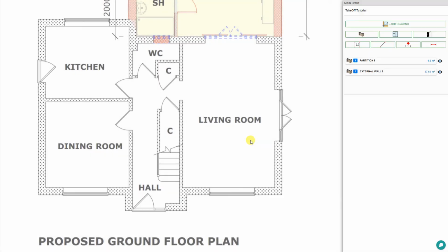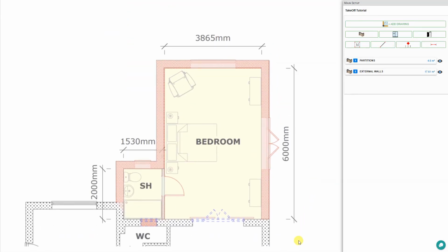Another handy tool is setting the wall shape. For example, this wall here may be gabled for the roof. So what we can do is select this wall, and then here we have the wall shape. If this were a side wall, we would leave this set as rectangular. However, as the end wall, we would need to set this as gable to accommodate the roof peak.